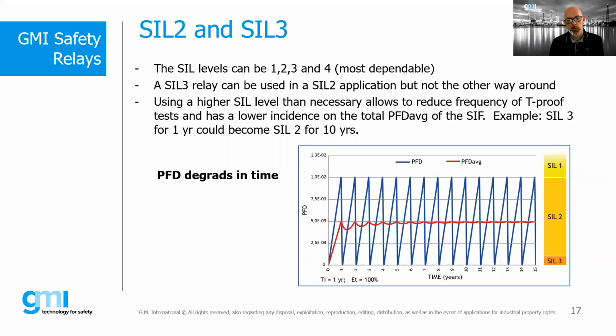And we have a question from one of our attendees, who asked: what is the PFD? PFD means probability of failure on demand. When there is a demand, you want to open or move a contact, and there is a probability of failure that the device will not perform that function.